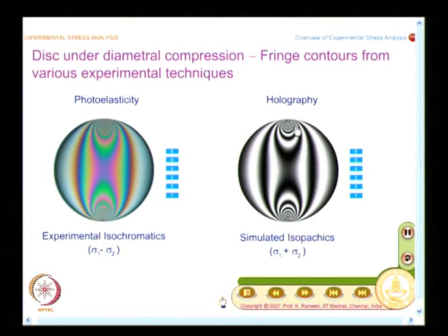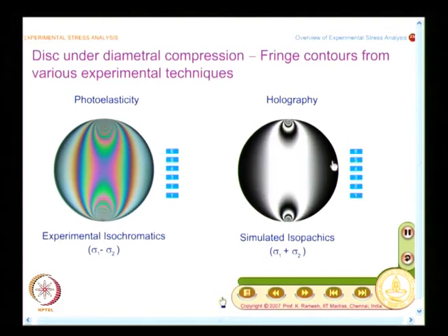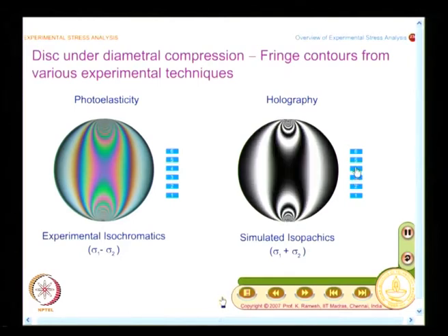And here you have this as a shape of 8, this as a shape of 8, this you have to note down, we will use it in our experimental interpretation later, and you can also see as a function of load applied how the fringes develop. So, what happens is fringes develop here and move outwards, that you could see from these simulations.